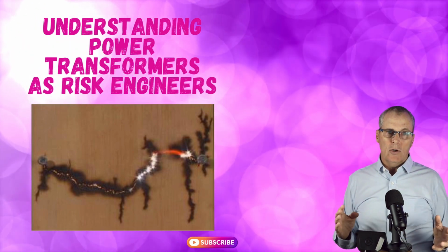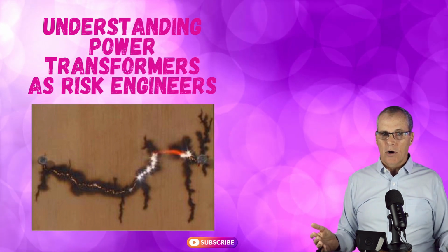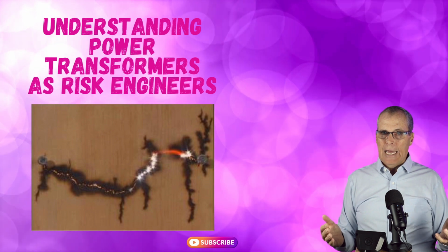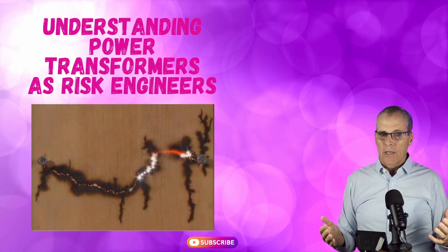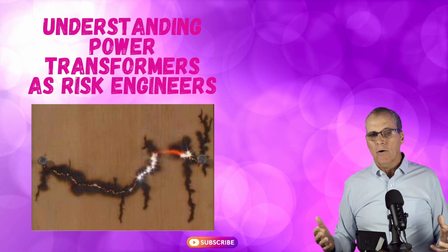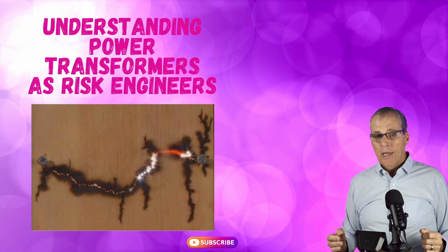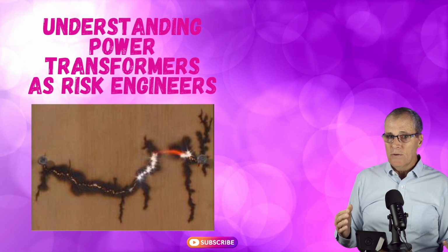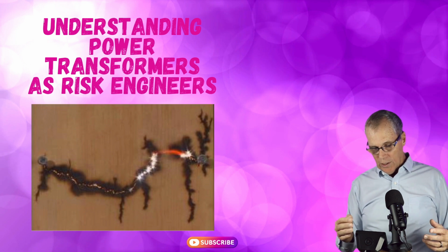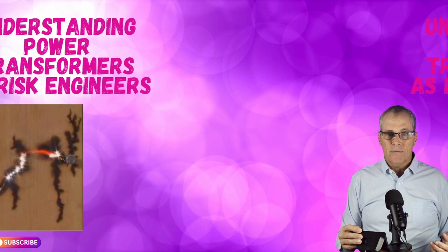This picture just shows you what partial discharge looks like. It's lab created partial discharge, but what starts to happen before the arcing, you see all that black coloration. That's carbonization, and it's growing across a piece of paper, and it's very conductive. It's ready to conduct electricity, and this is the state that it's partial. But when it goes to full discharge, that's when the arc happens.